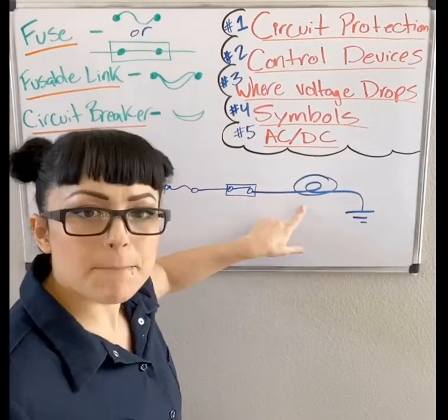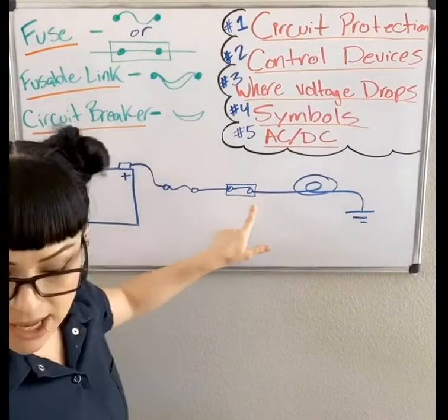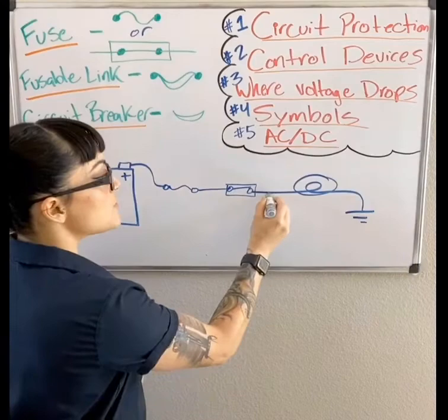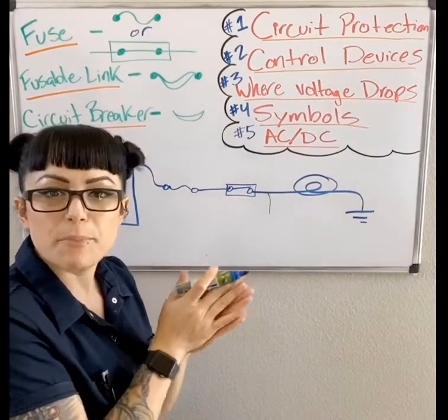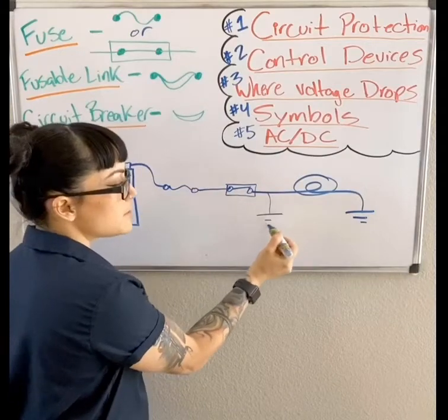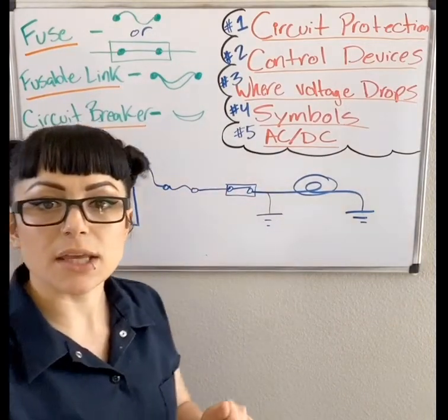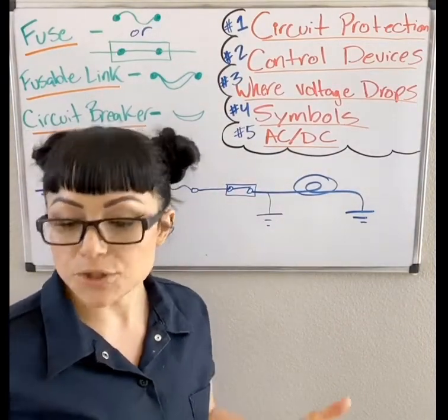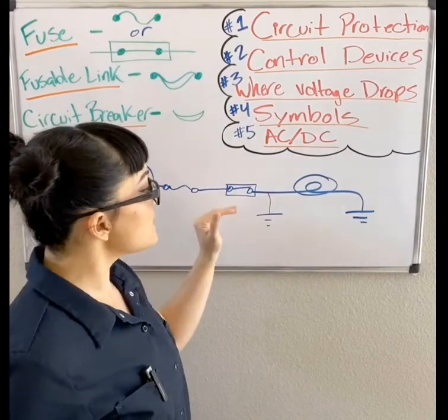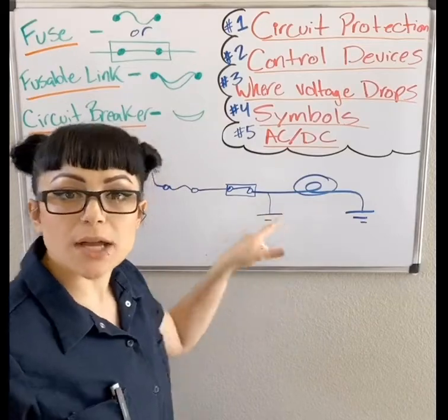What happens if I bypass that? And let's say, and again, we'll talk more about this later, what if some wire rubbed through, the insulation rubbed through so it's bare bare wire, and it touches somewhere bare metal on the chassis, engine, somewhere like that? Electricity is lazy and it will take the shortcut and go straight back home.